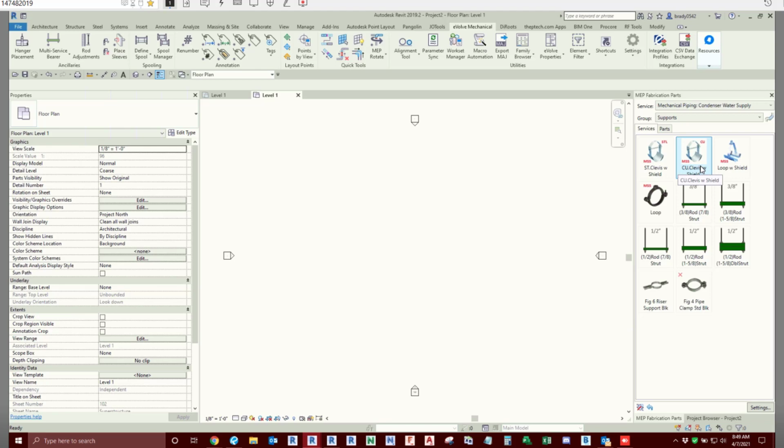Now again, sheet metal guys don't have to worry about this so much, but just note that if you are a plumbing piping guy, depending on which project and which system you're running, the rod sizes change even for the same material. There's something called the MSS standard. SP69 is the division specifically that dictates that. But you have different hanger spacing for steel than you do for copper, even of the same pipe size.